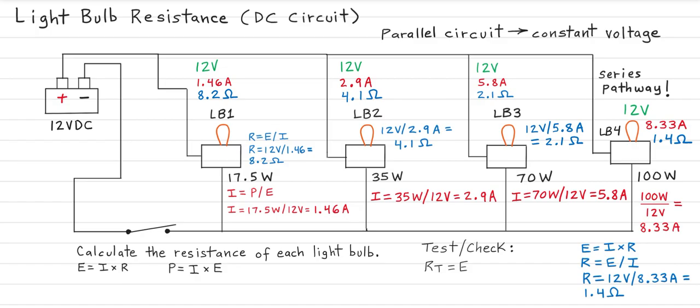So if you can quickly calculate DC circuit values, you could actually troubleshoot electronics super fast with or without a multimeter. To an extent, you might have to check for grounds, you might have to check for continuity, etc. And those assumptions are proven as true, but you can pretty much cut to the circuit pretty quickly. So this is the training part. So after you understand the fundamentals, you probably don't have to keep checking.